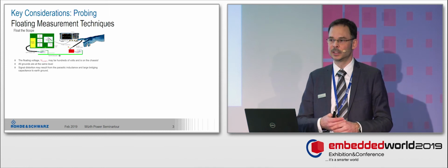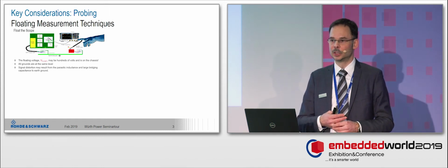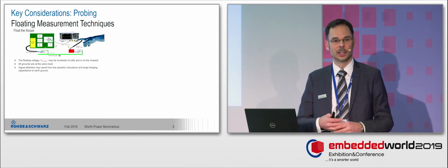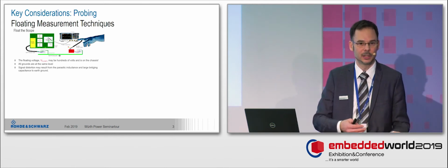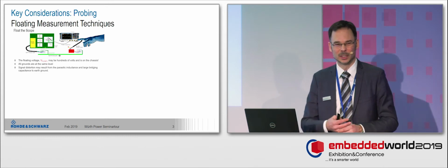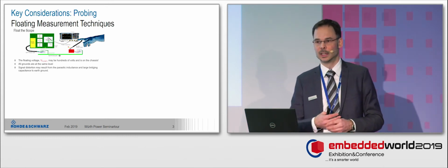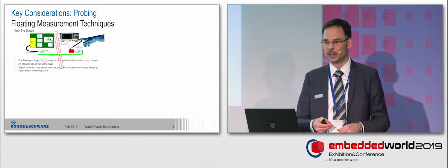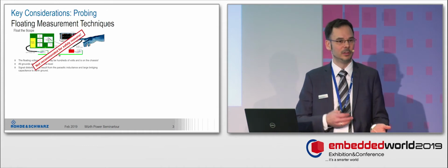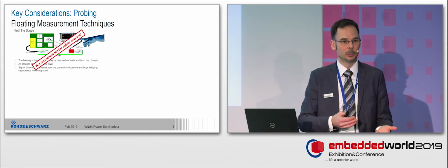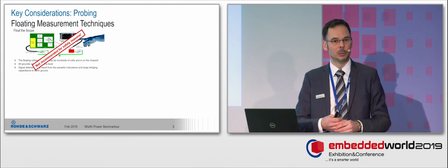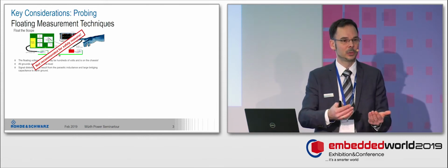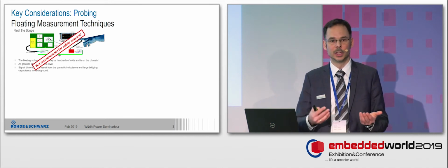One of the difficulties there is that actually you might get large voltages on the chassis of the instrument, so it can be dangerous. And there are some other disadvantages, which I will touch on the next slide. So that's the reason why we cannot really recommend it for safety reasons. There is one exception. Sometimes it makes sense to have a test setup where you have instruments behind the safety screen, and that's of course a situation where you can do that.